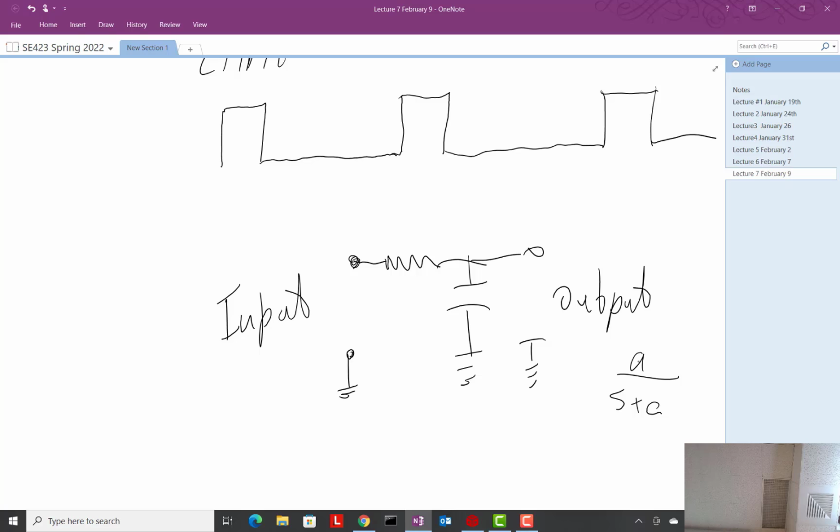Okay? When we're dimming and brightening the LED, it's our eyeball that's the time constant. If we had a high-speed camera, you could probably see the LED going on for a little bit of time and off for a little bit of time. But your eye can't see that. That's the time constant there. So I think in the homework I asked you to do it at 5 kilohertz. And your eye can't see that LED being off for that 0.2 milliseconds or whatever, or however much it's off. Right? Or on, right? So you're the filter, your eyeballs are.